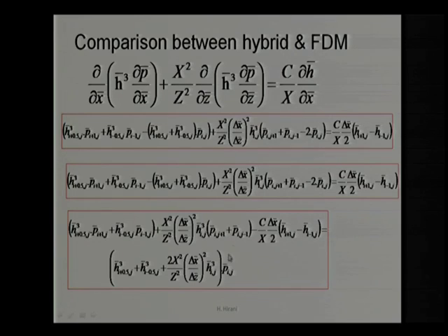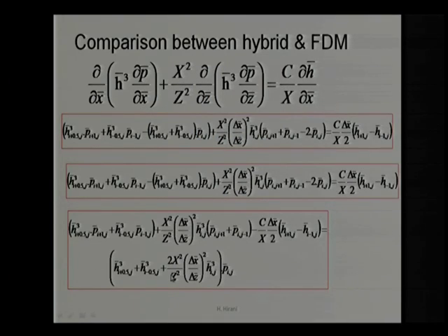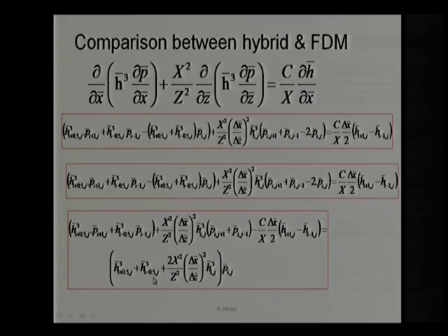We are just rearranging now. We know very well this is a Pij, and on the left hand side not a single term contains Pij, while on the right hand side only the terms contain the Pij pressure profile, and all others are geometric constants, which will not vary with iterations. However, all the pressure terms will vary with iteration, but all other terms will remain constant.